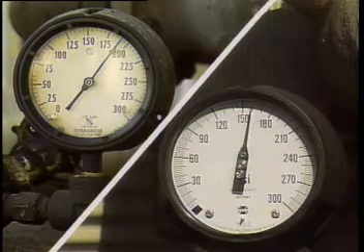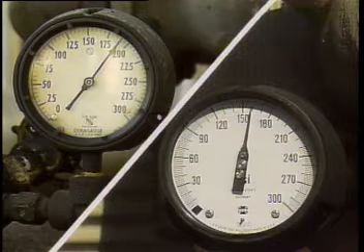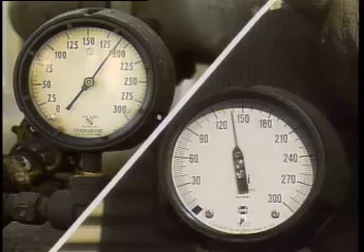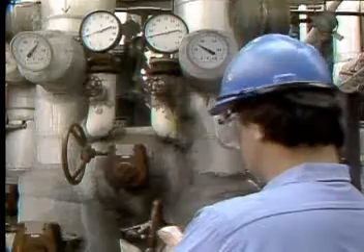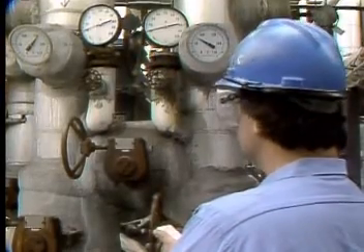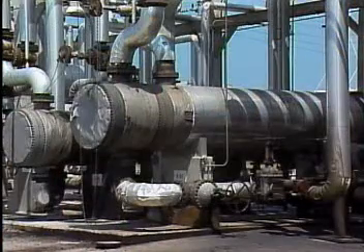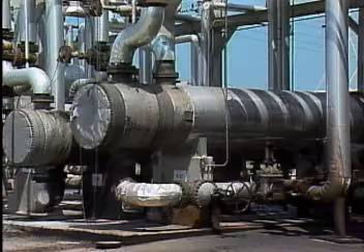This problem may show up on the heat exchanger's instruments as an increase in the pressure drop or as a gradual decrease in the flow through the affected side of the unit. Fouling may also affect the temperature of both fluids passing through the heat exchanger. When fluid flow is restricted, the heat exchanger must be cleaned.